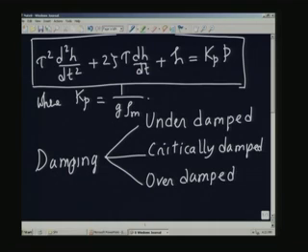So, what are the differences between these cases? In the case of an underdamped system, the liquid is going to undergo periodic oscillations. Flow is periodic, that means it will go up and down and then finally settle down. In the case of a critically damped system, it will just approach the steady state value from one side. And the overdamped case is similar, but it will take a long time for the value to settle down to the steady state value.